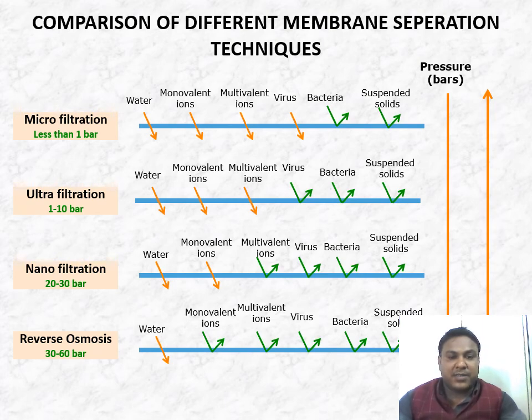Membrane processes cover a group of separation processes in which the characteristics of a membrane, on the basis of porosity, selectivity and electric charge, are used to separate the components of a solution or a suspension. The different membrane processing methods, that is microfiltration, ultrafiltration, nanofiltration, and reverse osmosis, are compared here and depicted in the figure to recognize the differences early. Here in the diagram of the comparison, these are categorized on the basis of pressure in bars and operating pores.